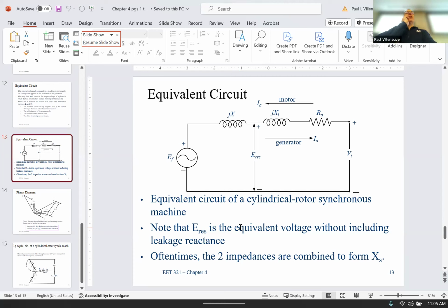Not that intersection per se. But remember, this is our excitation. We adjust the field current and we're going to get a supposed voltage over here. This is the output voltage that we're going to get. We only can measure this voltage if the voltage drop of the system is 0. So by doing the open circuit test, that does allow us to get our voltage here, right? So we can get the voltage there.